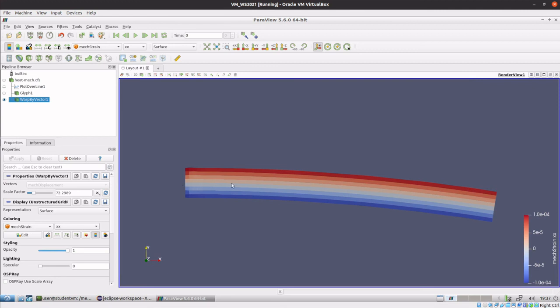So this center line does not expand in X direction, or does not get longer, that's the better term to use. This center line won't expand or compress because it already has the reference temperature. The top surface expands, the bottom surface compresses, but the center line has zero elongation.